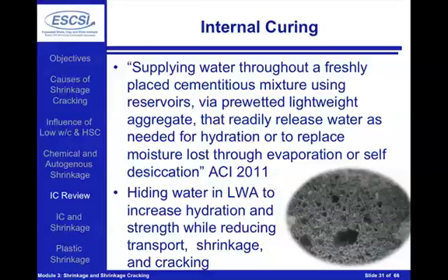So by hiding water in the lightweight aggregate, that water is going to come out, it's going to fill in the vapor-filled space, it's going to increase the hydration of the cement, of the supplementary cementitious materials. By doing that, it's going to increase the strength of our concrete, it's going to reduce the transport properties of our concrete, and what we're specifically talking about in this module is it's going to reduce the shrinkage and reduce the shrinkage-induced cracking that occurs inside of these materials.